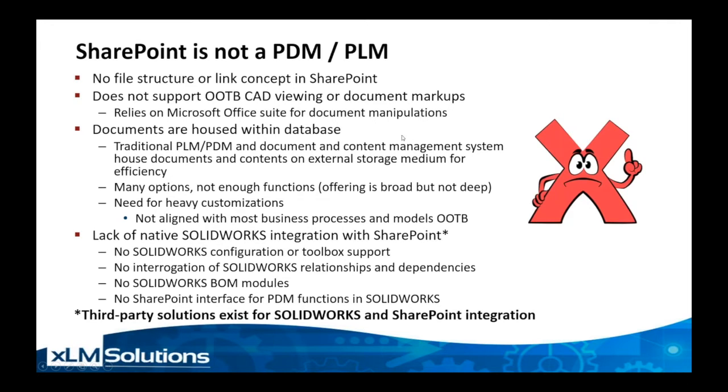When you do load data to SharePoint, the documents that you load are housed within the SharePoint database. They're not in a separate vault structure on the operating system. So with SolidWorks files that can get fairly large, that database size can grow fairly fast.